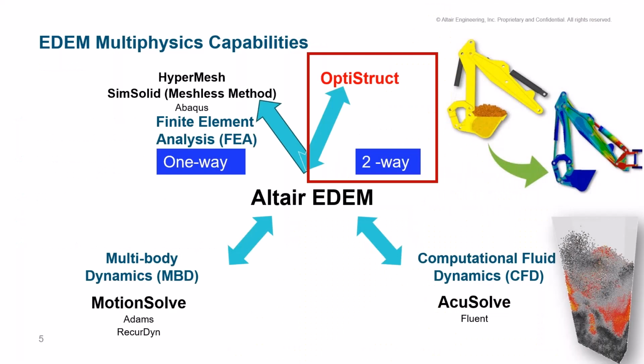Coming to the multi-physics capabilities, EDEM can be integrated with different simulation products. EDEM can be coupled with computational fluid dynamics solvers such as AcuSolve and Fluent as two-way, to study bulk material behavior under the influence of fluid.